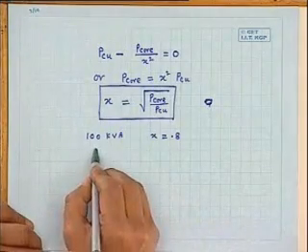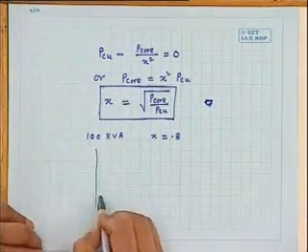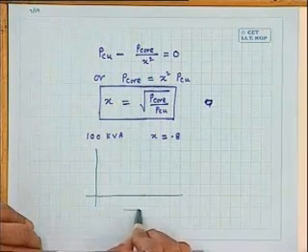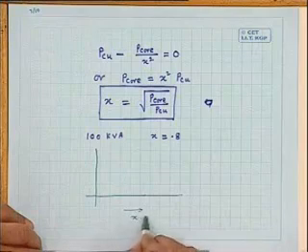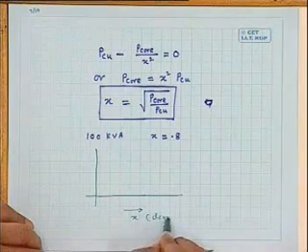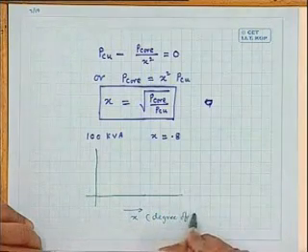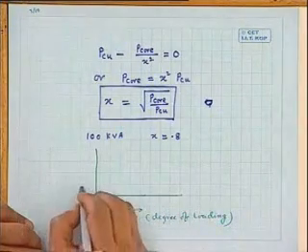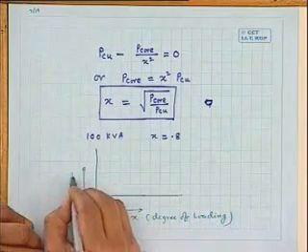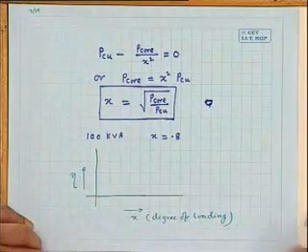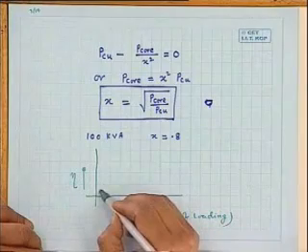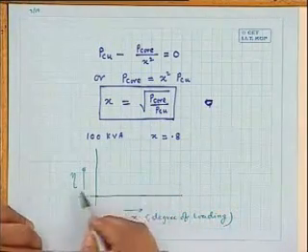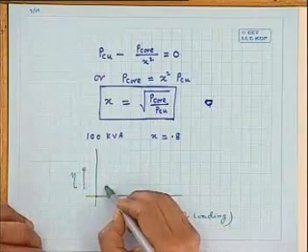But now, if you plot this, on this side the degree of loading x, and on this axis efficiency, eta, then this curve will look like this: at zero loading the efficiency is 0, because output is 0. It will pass through the origin.